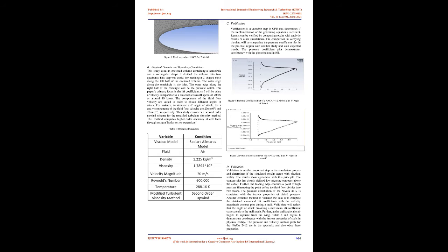Eddy viscosity is the internal friction between fluid particles which are moving randomly. It depends on fluid density, and it relates the average shear stress, stress acting parallel to the area, and the vertical velocity component. This model is effective for modeling fluid flow within wall-bounded volumes, so it was an effective method for simulating turbulence within a virtual wind tunnel.